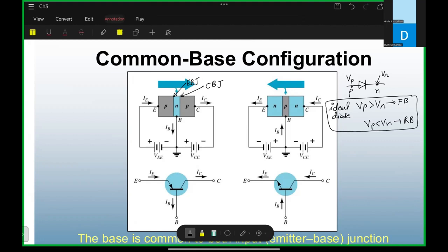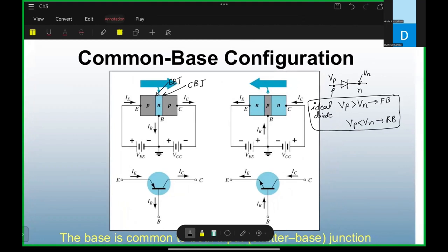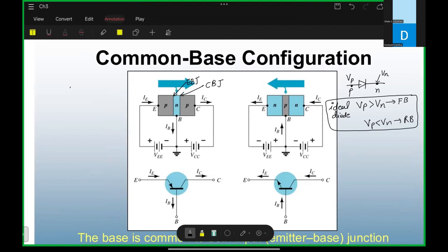Okay, back here. Inside the transistor these two junctions are there. The first junction is the emitter base junction. The second one is the collector base junction. If both the junctions are forward bias, then your transistor will be in saturation. In which region? Saturation region. What are the conditions for saturation region? Both the emitter base junction and collector base junction should be forward bias. Understood? Yes.